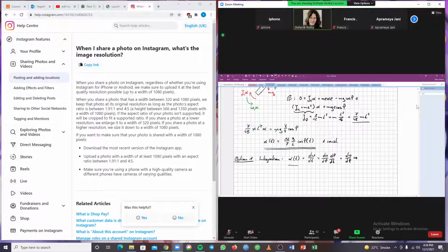Now, we multiply this equation by d phi, and we obtain omega d omega is equal to alpha d phi, alpha being time dependent. And now we integrate both sides of the equation. We start from rest position, then angular velocity and acceleration are 0, and we will integrate through an arbitrary position, omega and phi.